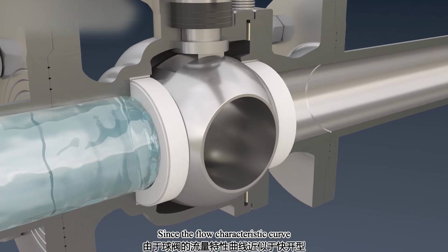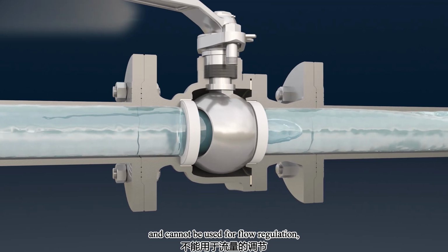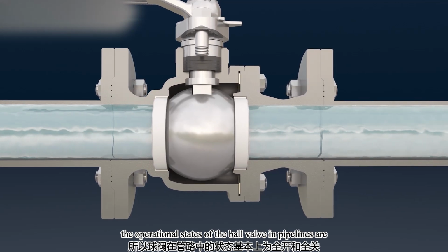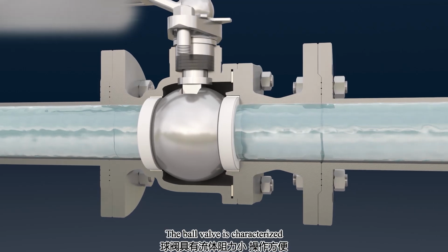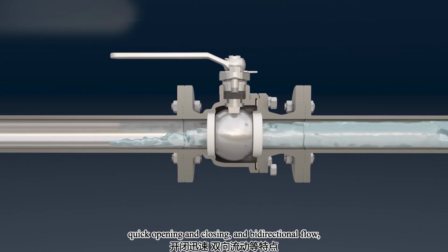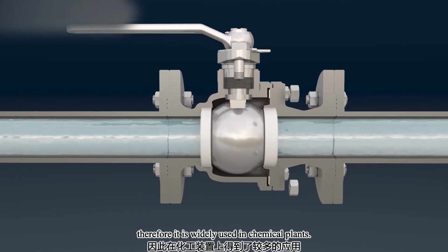Since the flow characteristic curve of the ball valve approximates the quick opening type and cannot be used for flow regulation, the operational states of the ball valve in pipelines are essentially either fully open or fully closed. The ball valve is characterized by small fluid resistance, convenient operation, quick opening and closing, and bidirectional flow. Therefore, it is widely used in chemical plants.